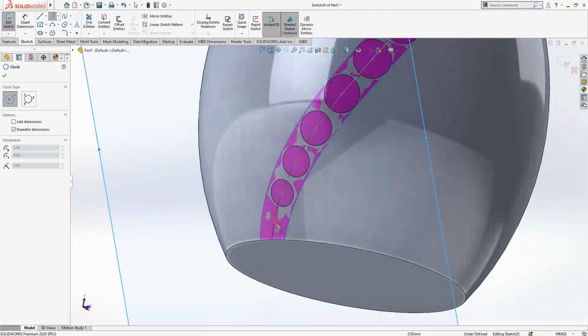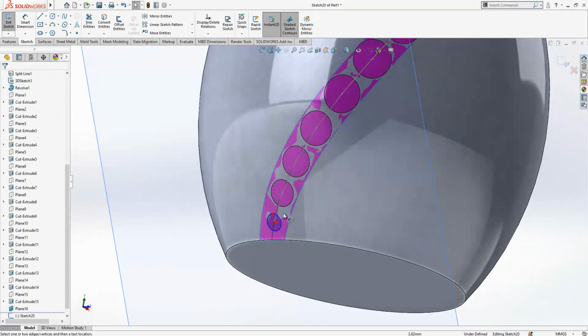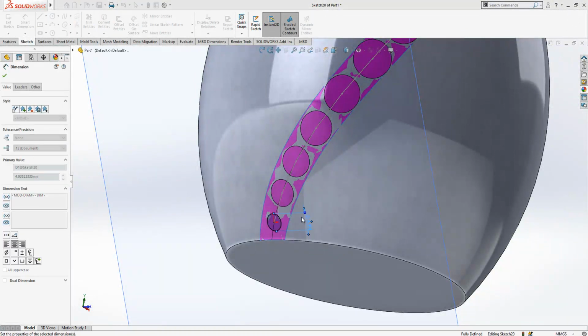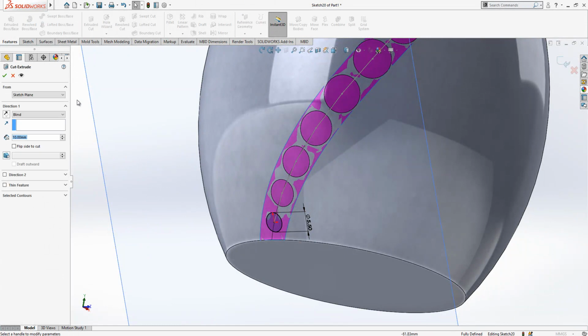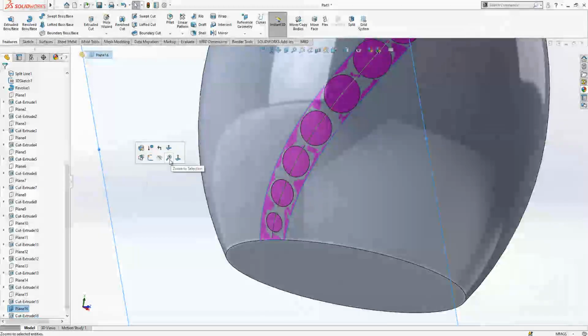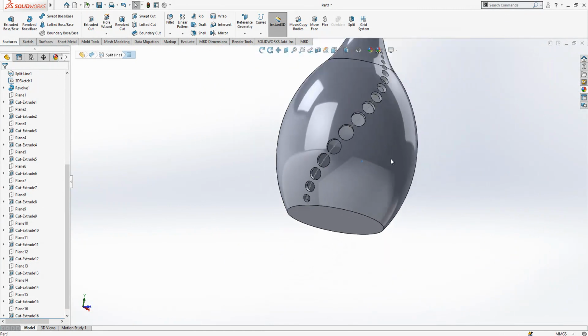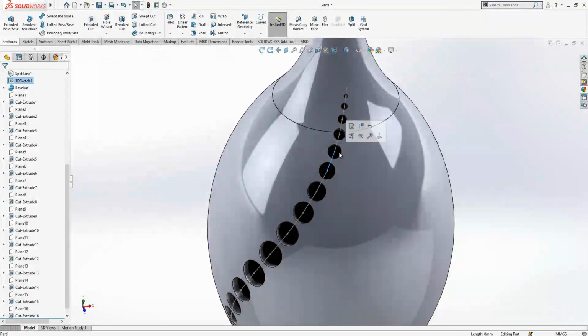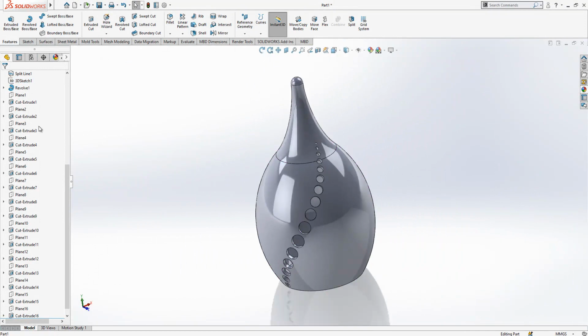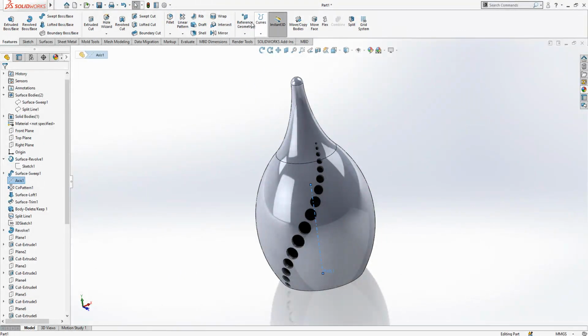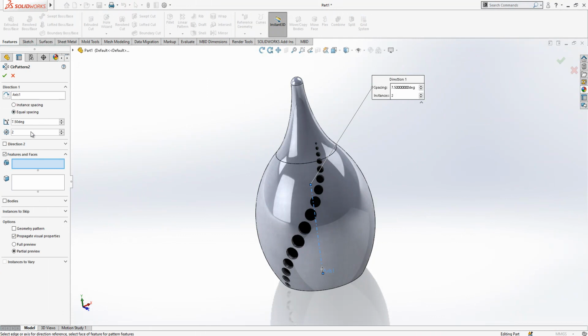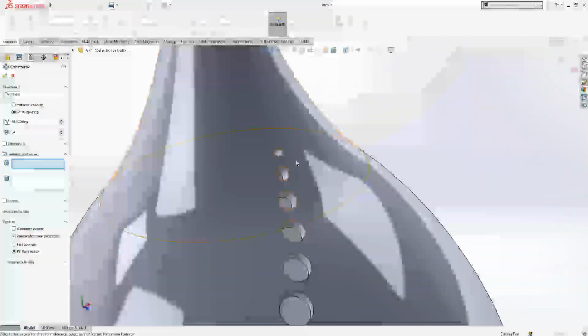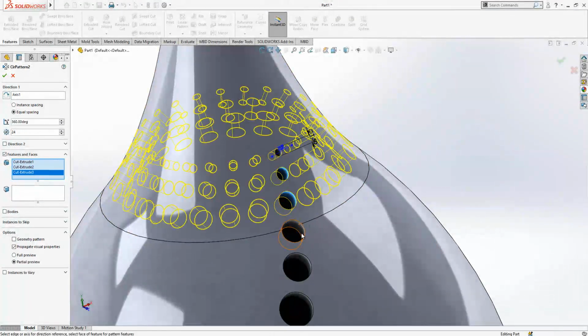We will add some little details. Here now we have 5.5. Yes, what we have done now, simply we create unequally distributed holes, and then we will copy them, axis here, circular pattern, equal spacing, 360. If you make 24, will be all right. Each hole selected.